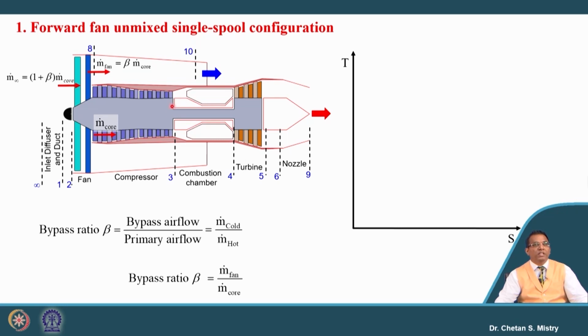Here in this case we have our initial component, that is the inlet duct or inlet diffuser. So, on our diagram let us put this. Now, you are expert enough to understand the ideal cycle and actual cycle. So, let us discuss the ideal configuration. The air will enter from the intake and gain some pressure in the intake, where there is a deceleration of flow.